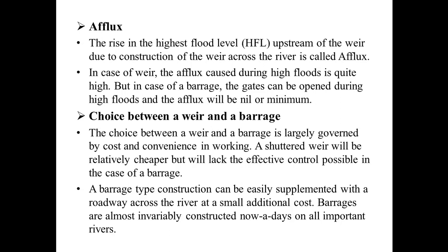If you have a choice between a weir and a barrage, here are two points. The choice between a weir and a barrage is largely governed by cost and convenience in working. A shuttered weir will be relatively cheaper but will lack the effective control possible in case of a barrage. So the construction of a barrage or weir is largely governed by cost and convenience in working. Also, a shuttered weir will be cheaper than a barrage, but it will lack the effective control which we have in a barrage.